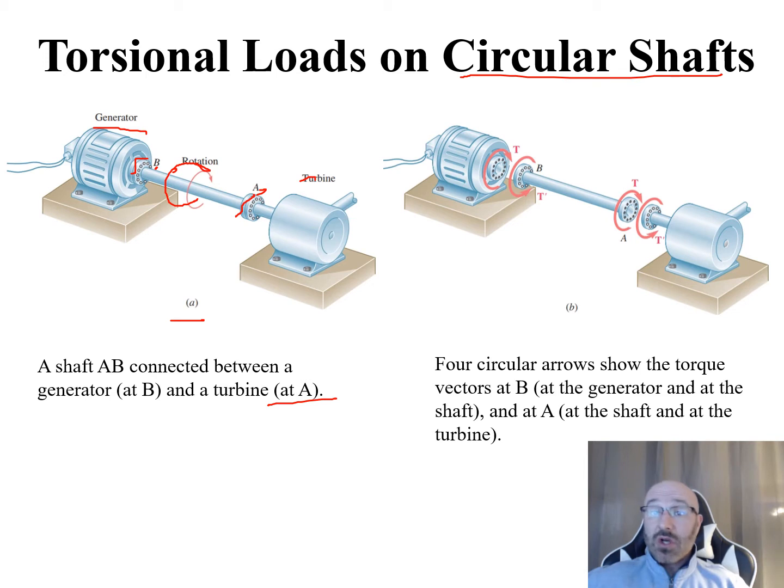So that's where we just talked about understanding what direction things are rotating, which direction is being resisted, is going to help us draw these torque arrows, these curved arrows in the correct direction. This is important here, that we're saying whether it's clockwise or counterclockwise, is positive or negative, depending on your coordinate system. Physically drawing these curved arrows in lets us know which direction it is rotating. And it doesn't hurt down below to say, okay, counterclockwise is positive or whatever it may be for your system here. So then we move over and we take a look at our diagram B right here.